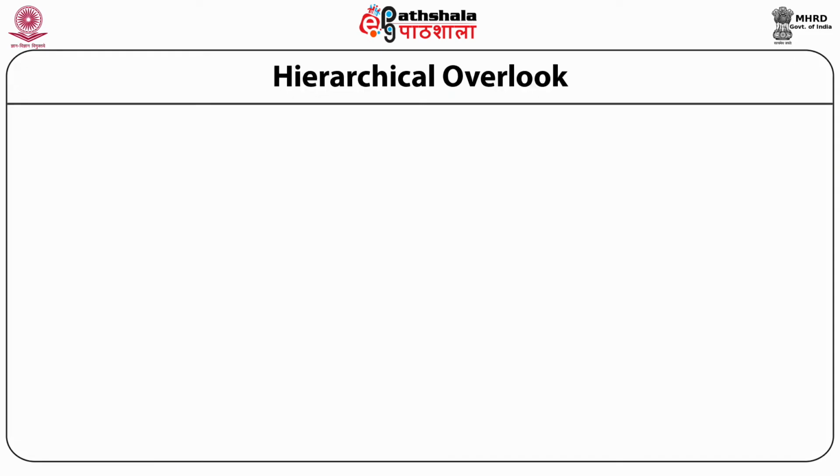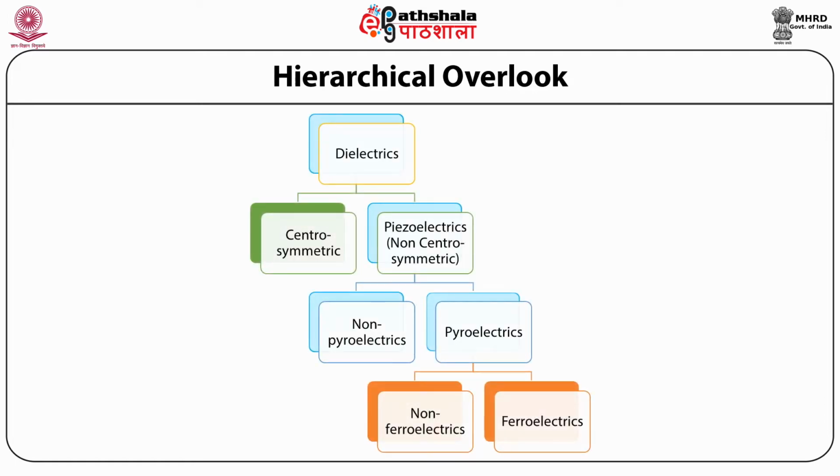Hierarchical overlook. So students, let us look into how the dielectrics have been classified. Dielectrics are classified into centrosymmetric materials and piezoelectrics, which are non-centrosymmetric materials. Further, these piezoelectrics are classified into non-pyroelectrics and pyroelectrics. We will be focusing on pyroelectric materials. Further, these pyroelectric materials are classified into non-ferroelectrics and ferroelectric materials.